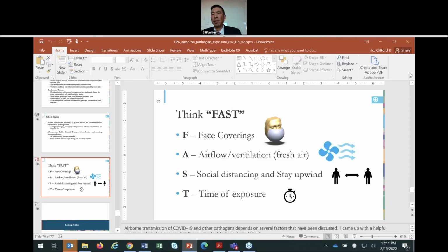My feeling, I've done some studies or evaluations of this. My feeling is that I call it dilution and deposition. The more you can provide the opportunity for particles to either be diluted with fresh air or to be deposited or filtered with filters in a central air handling system, that's just going to continue to help reduce the amount of concentration. So I think of whether you have a centralized air handling system or even these packaged terminal ventilation units that you find in hotel rooms, there are advantages and things to be aware of in each.